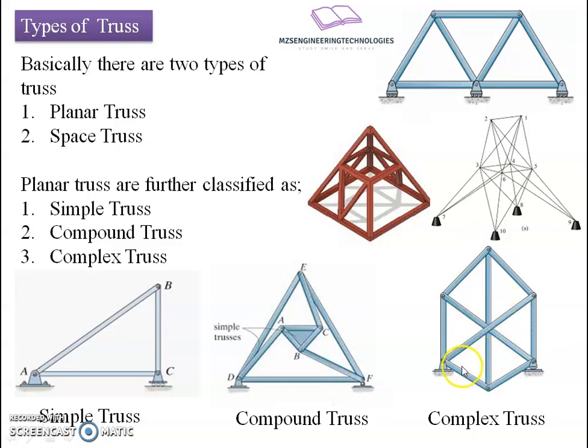The right hand side figure shows that there are n number of loops having connectivity, defining the loops inside it, but the ends, or the outer periphery, are shown secured with the help of pin connections, but at the crossing or overlapping elements we are not going to define any hinge here. Thereby it leads to a complex geometry, and it is a little bit cumbersome to find out what the forces are in that particular truss. Such type of truss is called a complex truss.